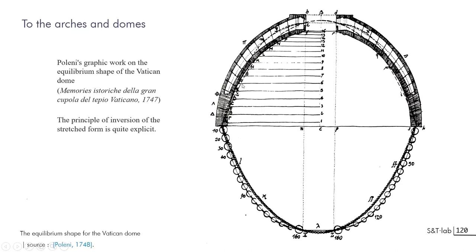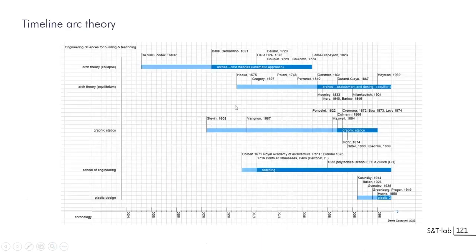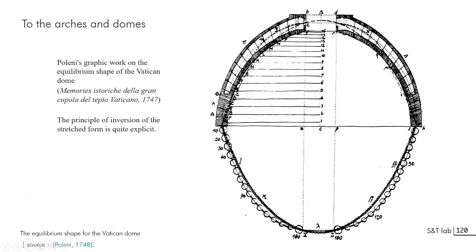It will drive you to a force here that's going out of the line of the thickness of the arch. And if you go more in detail in modeling the concentration of loading on the side or in the middle as heavier balls, you can have a new line that is just fitting inside the geometry. So that will become later the theory of the thrust line.